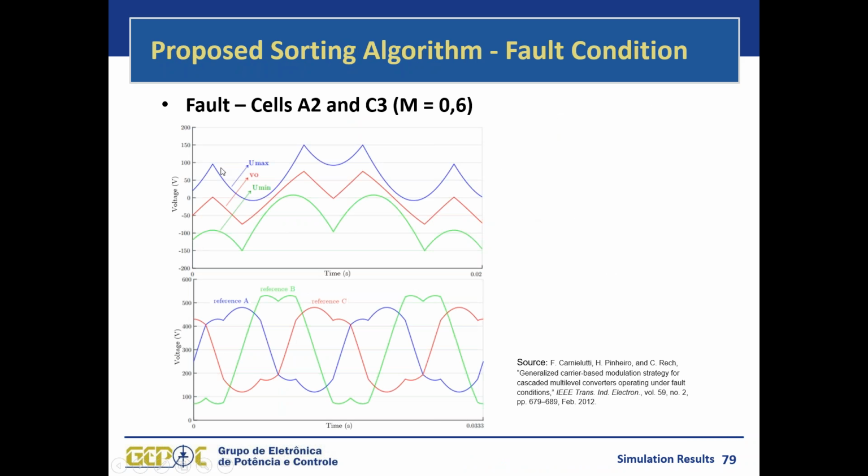So we can calculate the linear region for the inverter operation without overmodulation, and we can find this common mode voltage here that is going to be added to the voltage reference that would be sinusoidal. So adding this common mode voltage to the balanced sinusoidal references, we have this other reference here for phases A, B, and C.